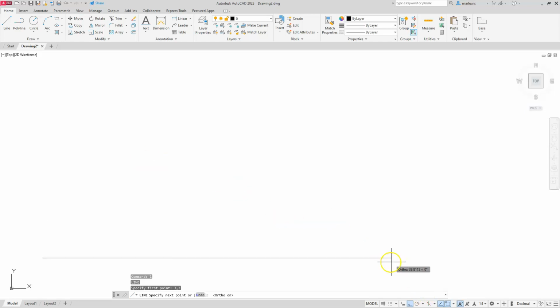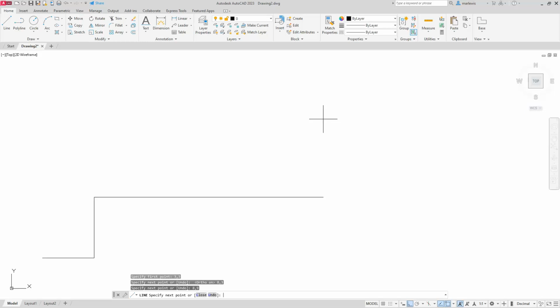Now for me creating this shape, if I'm using the absolute functions, I can have this turned on or off. It doesn't matter. As a matter of fact, I can put my cursor up here and I don't even have to touch my mouse anymore. I can just type in the next quadrants. So I'm going to type in 8, 3, enter. Then I'll type in the next one, which is 8, 9, enter. And then I can type in 3, 9, enter.